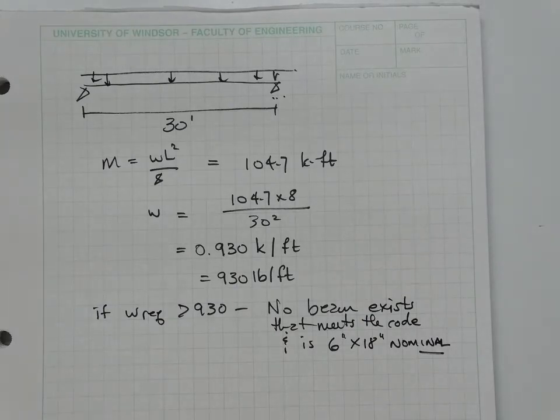Why is that there? And since our moment of inertia is going to vary only with the width and not with the cube of the depth, deepening is way more efficient. In fact, widening the beam only increases our value of b. That doesn't help our lever arm. We want to deepen the beams all the time to increase their capacity. So what if we can't do that?